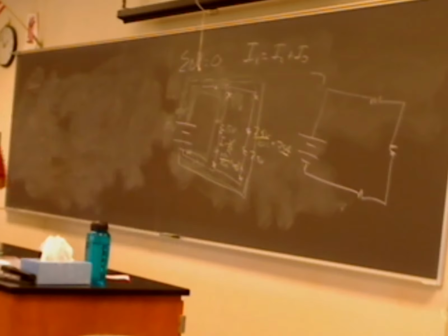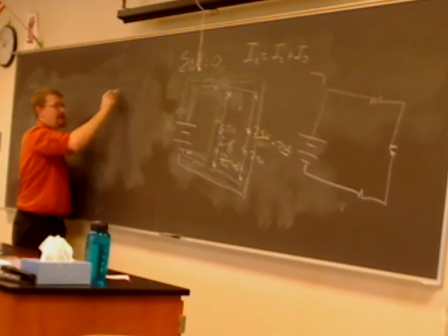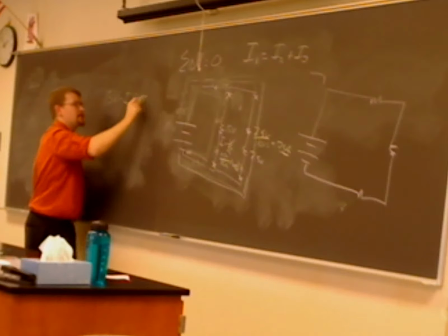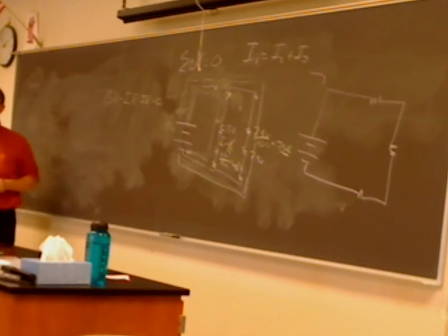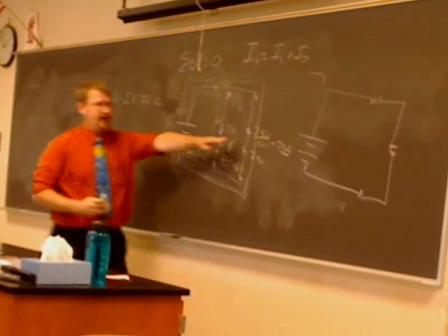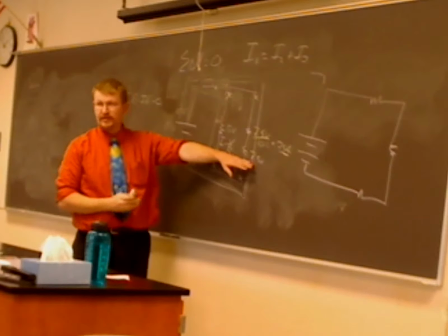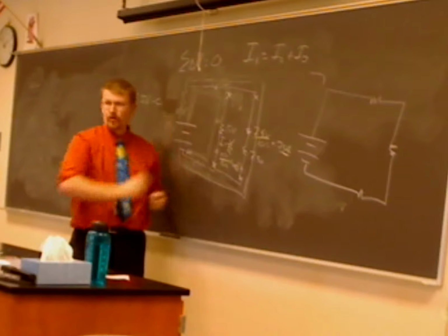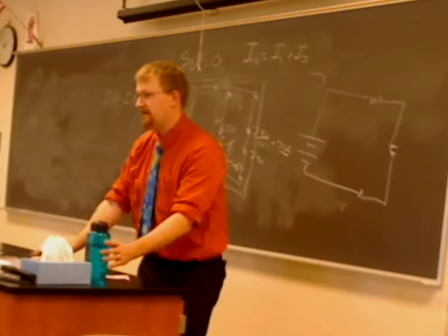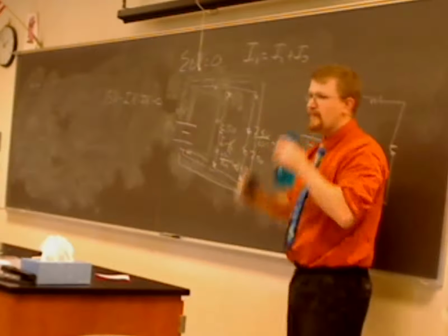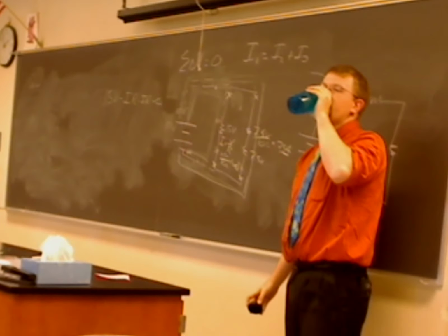What if the resistors weren't the same, and how do you figure out the voltage by proportions? You can; the shortcut way would be proportions. The official way is we do this every day. I think they call these loop equations. Technically, this is how we should be doing it, but since they are all the same, we can kind of cheat in our heads. I mean, if this was a 10 ohm and a 20 ohm resistor, I could probably pretty simply say it was 10 and 5. But as it gets more complex, you'd have to rely back on your actual mathematical method. Yes. But it will break proportionally in the end. So voltage gets split